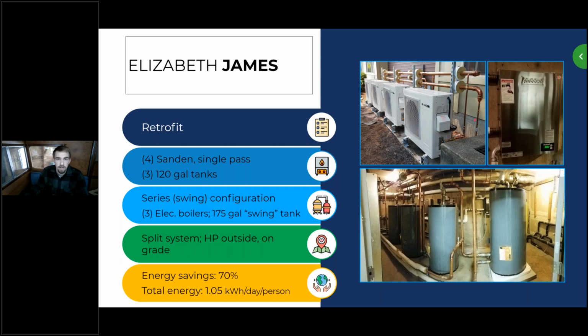And then from there, the hot water is charged into these 3 primary storage tanks, which are plumbed in series to allow for maximum stratification inside those tanks. So plumbing the top of the first tank to the bottom of the second tank and so on will allow this to act as one tall storage tank, so you can charge the top of that tall tank with hot water and the cold water remains on the bottom.